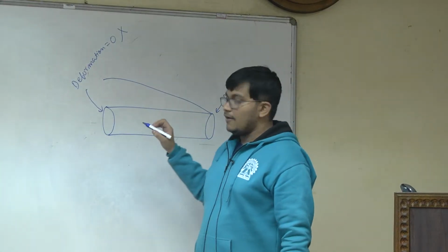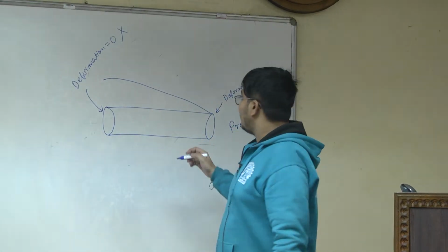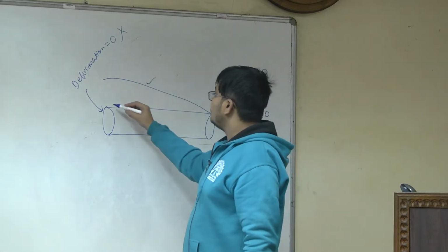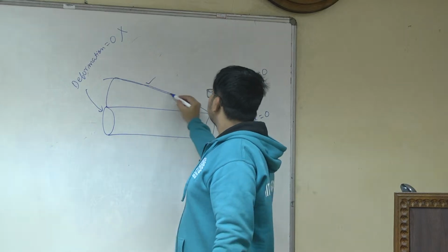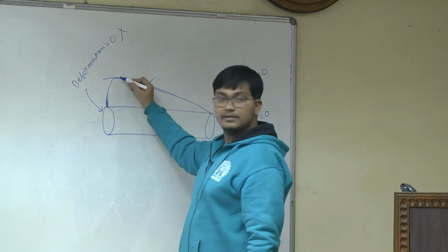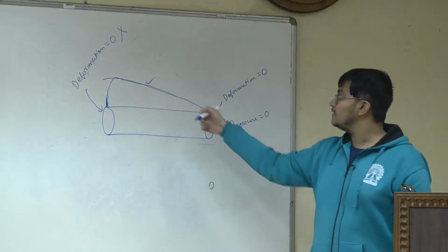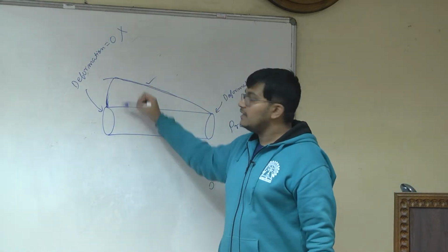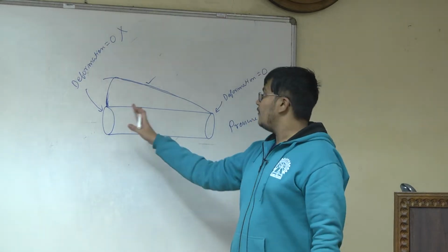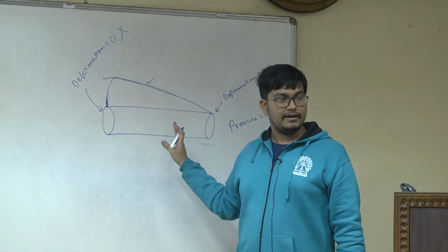After simulation in Ansys, if this is the correct profile, Ansys will give you a result something like this. Here this is the wall, and then the wall suddenly achieves that height, so near the inlet the results we get will not be correct, but away from the inlet the results will be correct.